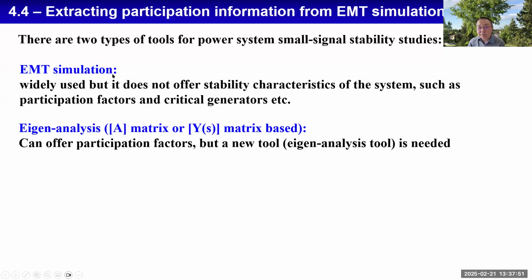One is EMT simulation like PSCAD, widely used, but it does not offer stability characteristics of the system, such as participation factors or critical generators. Another tool is eigenanalysis, which is state matrix based or impedance matrix based. It can offer participation factors, but you need to run a new tool.